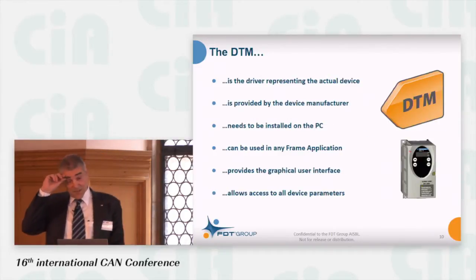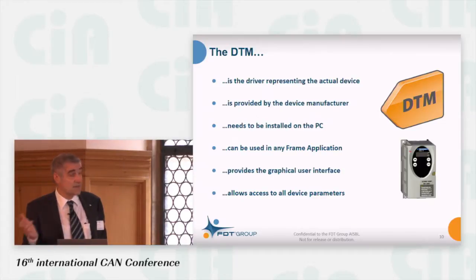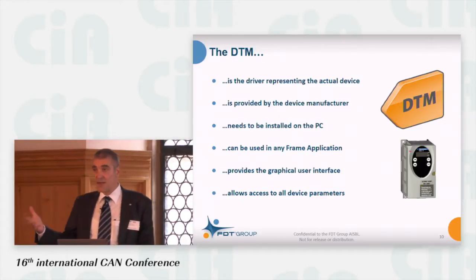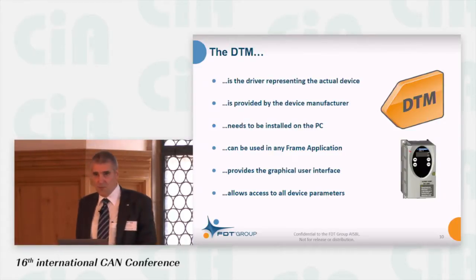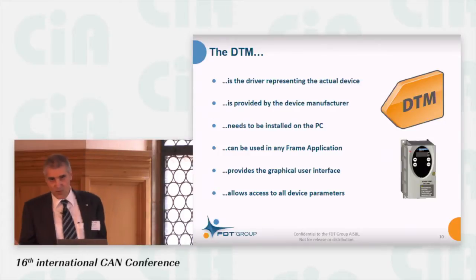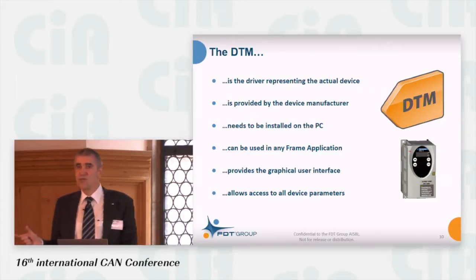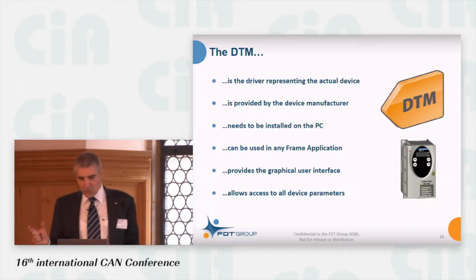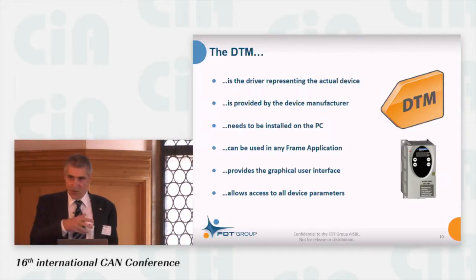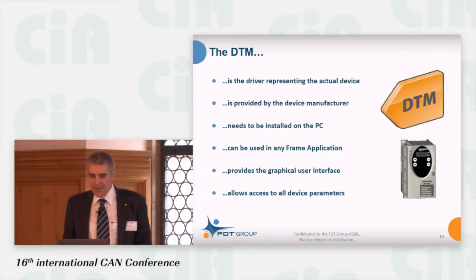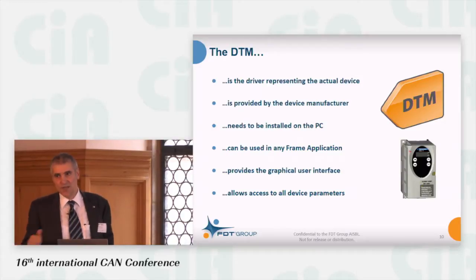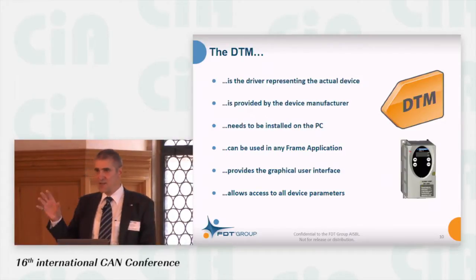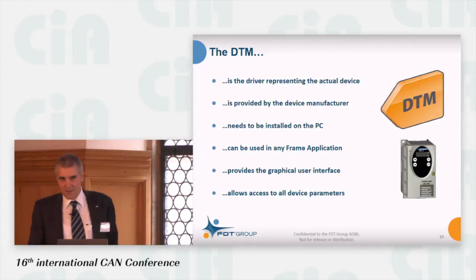The DTM itself, as I said, is like a driver and represents the actual device in the frame application. The manufacturer provides this because he talks to his device and exactly knows what this device is able to do. The DTM is installed on the frame application system, and the DTM can be used in any frame application. Due to the standardized interface, a DTM can run in different vendor engineering or asset management tools.